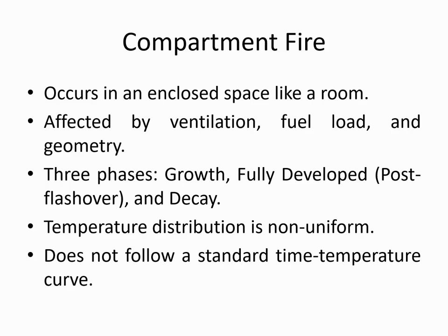This component fire has three phases. First one is growth phase, second one is post flashover phase, the third one is decay phase. Unlike the standard test fire, the component fire does not follow a fixed temperature curve. The temperature distribution is uneven and changes dynamically, compared with furnace fire or the standard fire test, which is taken in any laboratory or institution.